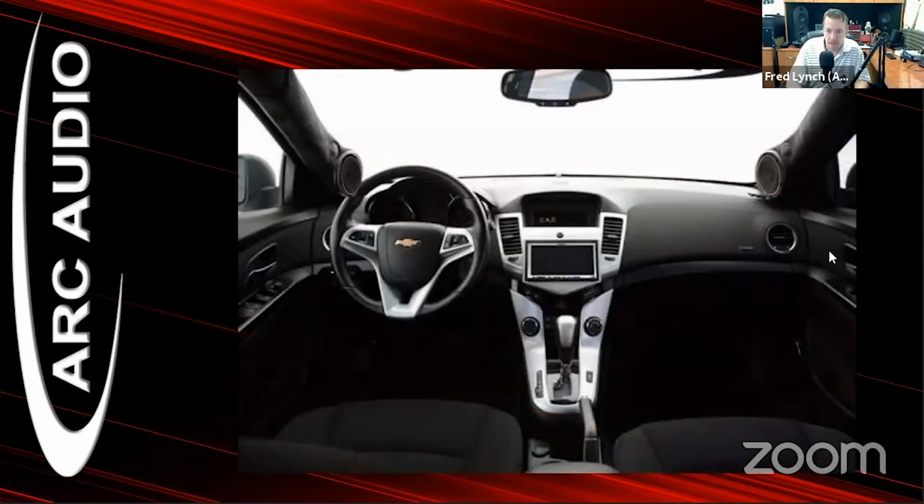Here we go. So in this case, we have all of our speakers in the system, and we need to focus on remembering where our crossover points are. I probably should have put a slide in here to reiterate where we were with the crossover points before. So our tweeters are basically 5500 and up. Our mid-ranges are from about 5250 down to I think it's about 175 hertz in this one. Our mid-bass drivers are 165 down to 60, 65 range, and then our subs are below that. You have to think about the entire frequency spectrum and chop it up in pieces.